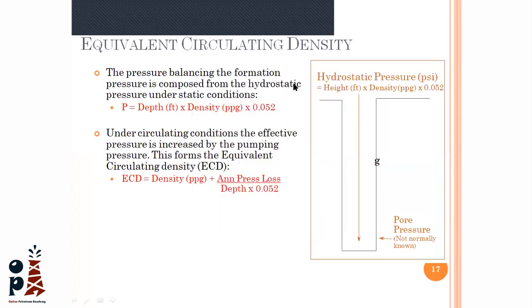Yes, of course. I will talk about my job. While we are mixing, it is my responsibility to provide the mixing recipe. So I have to calculate the mixing recipe. But for the pressure and the mud weight, and as I told you, it is the most important thing, it is the pressure control. So we get this from the drilling company or from the company that has the well itself. We call it the operating company. They provide the mud weight calculation and pore pressure calculation for us in the drilling program.